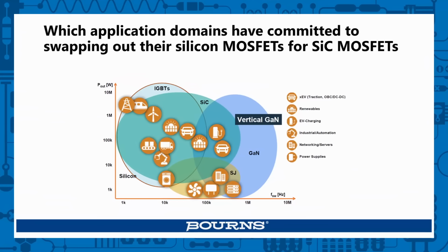And so with silicon carbide in particular, you can get modules now which are over 2,000 volts on the market. Gallium nitride is a little far behind in terms of voltages. I think you can get 600 volt gallium nitride on the market, but silicon carbide seems to be the one that's preferred for high voltage applications in the areas I was talking about, which would be renewable energy and solar, things like that.